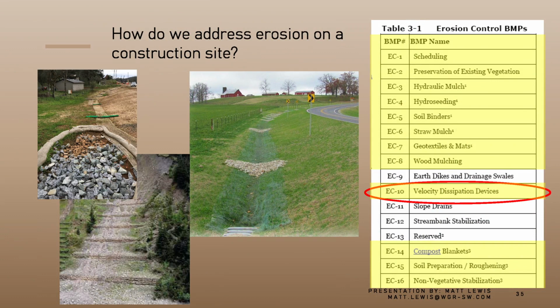I see this a lot of times on levees. You get hydroseeded and then you won't put any linear breaks, because pretty much the biggest battle you deal with when it comes to sheet erosion is velocity. When water starts to speed up, you're going to get much higher rates of erosion.